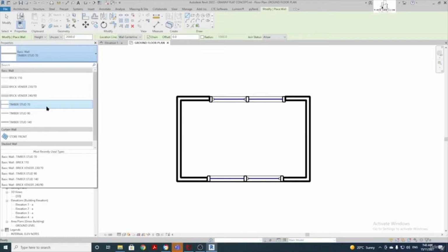So in Australia, most dwellings are brick veneer. So it's got like a 110mm brick on the outside with a 40 to 50mm cavity, like just an air gap in between, and then we'll have the stud wall, usually a timber or a steel stud. That's normally between 70 to 90mm, the stud. So that's why I've got these all set up like this.